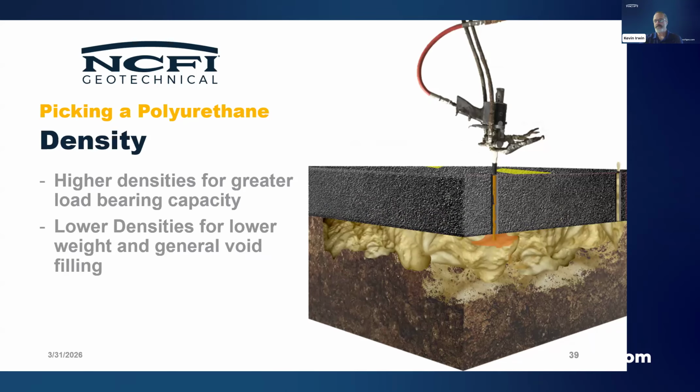Of course, picking for density, density is going to directly relate back to how much compressive strength we have. But density also very much affects our estimating as well. So lower densities for lower weight applications, general void fill, higher densities for greater load bearing capacity.